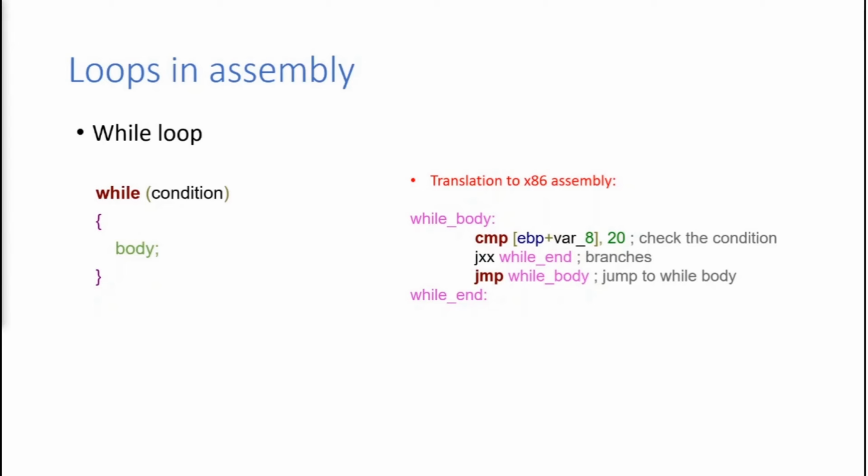The conditional jump is often preceded by a compare instruction. The CMP instruction compares two operands. It is basically used in conditional execution. This instruction subtracts one operand from the other for comparing whether the operands are equal or not. It does not disturb the destination or source operand. It is used along with the conditional jump instruction for decision making.